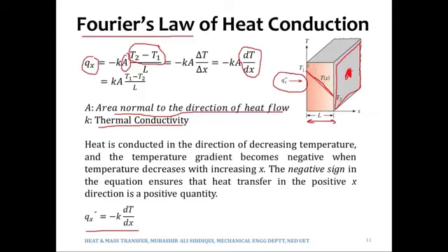For example, if this is the temperature variation that we have in x direction, what does this mean? It means that T1 and T2 are the same. And if T1 and T2 are the same, then no heat will be transferred in x direction, right? So what I am trying to emphasize is that we would have a temperature profile. We would have a temperature distribution depending upon the temperature values at the two faces, and also depending upon the thickness of the medium, and also depending upon the nature of the medium itself, which we will see later.